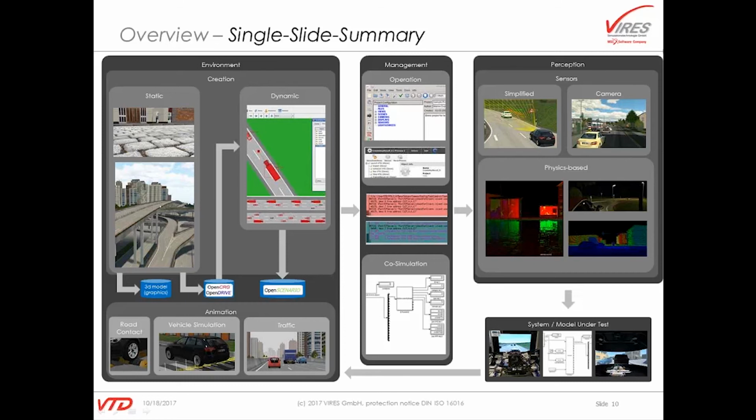And the sensor information that we provide may either be based on a simplified version, which is the typical object-based sensors. We can provide camera information, and we can go more into the physics-based sensor simulation, which I've shown in the video already with the LiDAR point cloud, and here some other pictures from a LiDAR simulation and from a camera simulation with a large number of light sources.